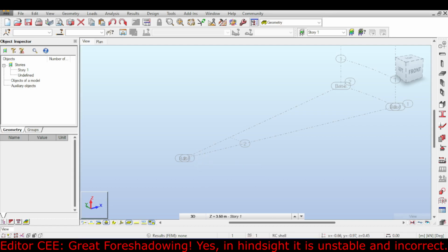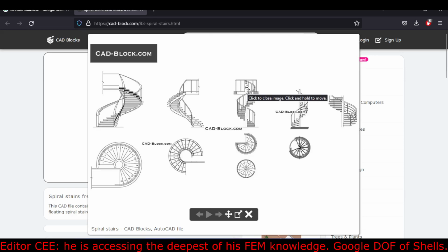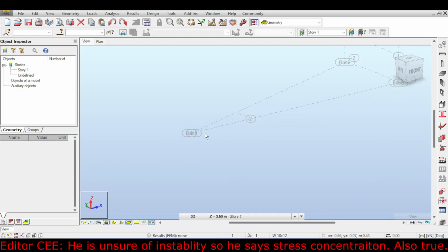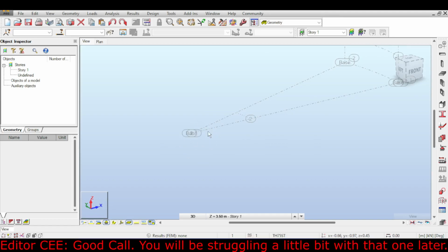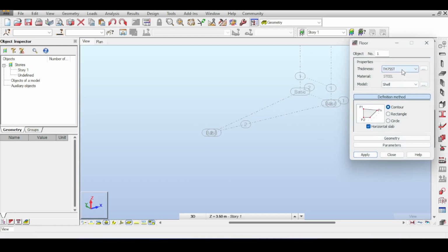Because, truth to be said, even if it is in a central pedestal, you still have the thickness of this thing that supports it. So for me, I will basically, I don't know what I will be doing. The problem is I have foresight, because if you use a point to connect to a column, you will have massive stresses here that are incorrect actually, because you have a surface area to weld to it. It's gonna be tricky. I'll think about this later. Anyway, for now, I'll just use a simplified modeling, and I'll talk about all the nuances later.